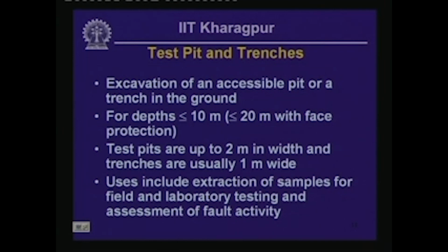So, what are test pits and trenches? Test pits and trenches are holes or trenches dug in the ground, excavations in the ground, and the depths of these test pits or trenches can typically extend up to about 10 meters.